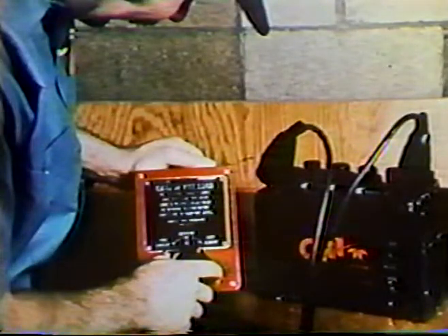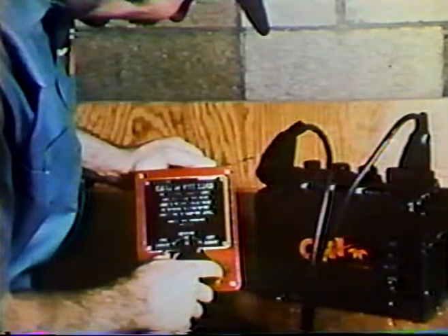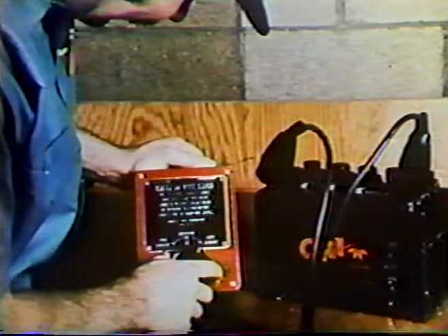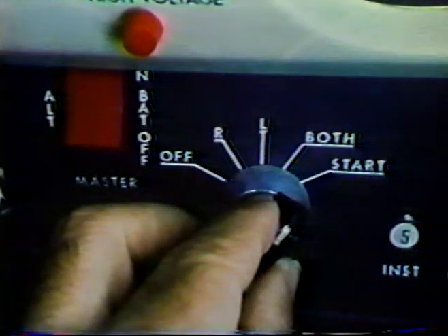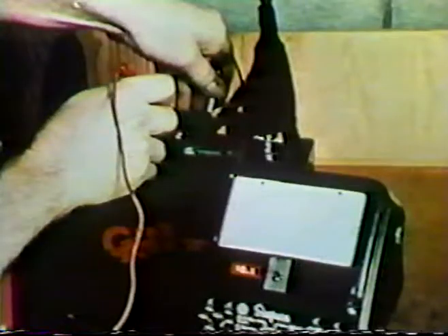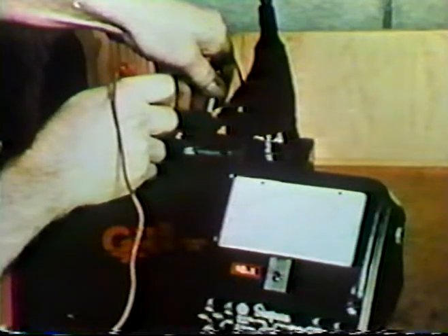If the battery is on the service bench, apply a load of about 150 amperes for 3 seconds. If the battery is in the airplane, crank the engine for 3 seconds, then apply a load of about 10 amperes or turn on a taxi light for 1 minute. Measure the voltage across each cell with a low-range voltmeter.